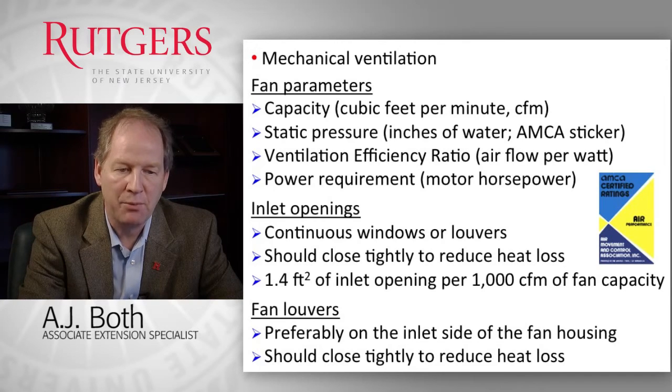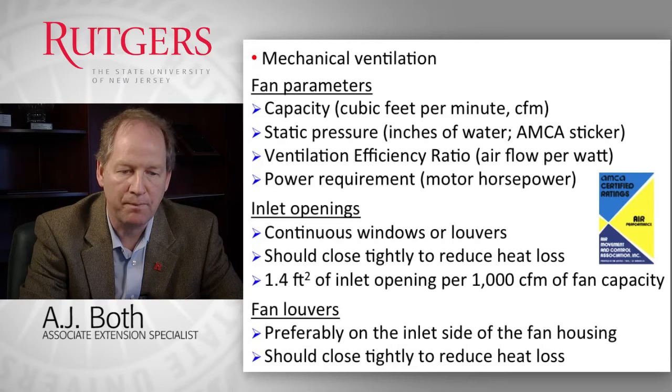Another parameter of the fan that's important is the ventilation efficiency ratio. So how much airflow is the fan able to provide for the unit of electricity in watts that the system requires to operate? So how efficient is the energy conversion? And finally, what is the power requirement? So how many horsepower does the motor require to operate the fan? So all these parameters are important to understand and to know before installing a fan system in your greenhouse operation.